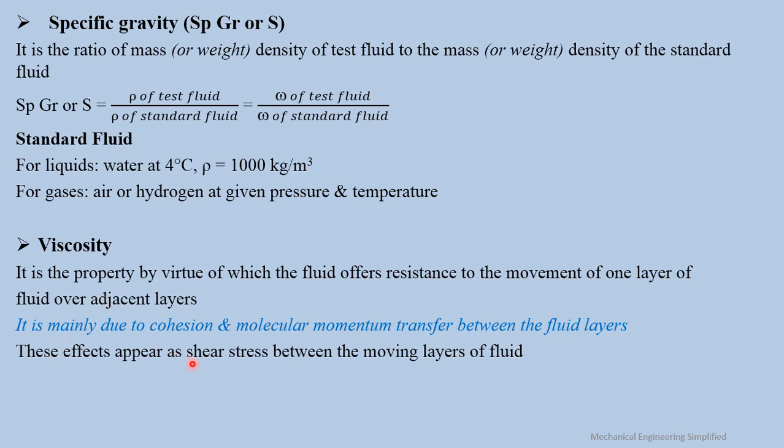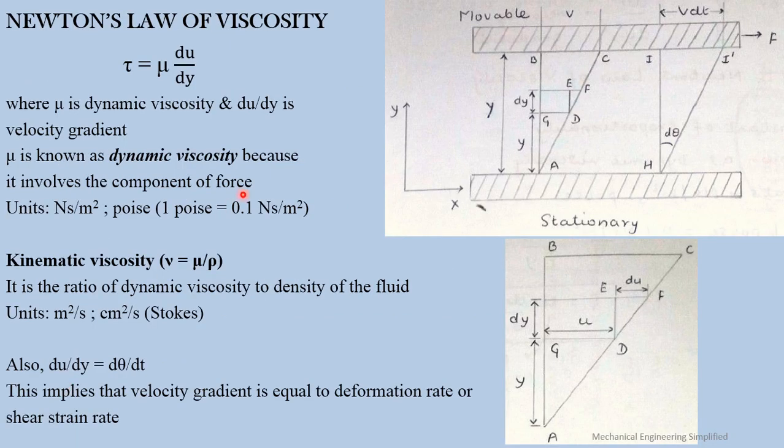These effects appear as shear stress, because as I have told you, the fluid cannot resist shear stresses or shear force at rest. However, when there is a fluid flow, shear stresses can be developed, and that appears as the property of viscosity. Then in viscosity, we have a very important law known as Newton's law of viscosity. How it is derived, I am not going into that derivation. That can be looked up in any standard book.